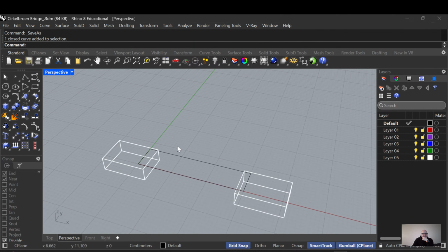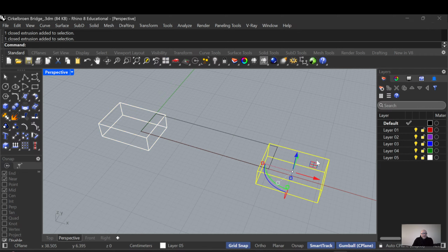I don't want to use any standard or metric system, so later on you can edit it and start a unit-based development, or after finishing it you can take it to any unit that you would like and rescale it again. These two white boxes are supposed to provide the shores or the landing pieces, and the rectangle shows the boundary for the bridge that we have.